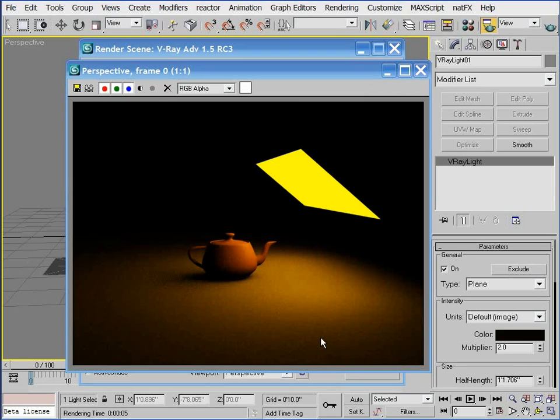color mapping. Values over 4 or 5 is what I consider high. I don't mean to say you can't use such values. I'm just saying that you should be careful when you use such high values because you're almost certainly going to have to use higher quality settings to achieve the same low level of noise that you would have with higher intensity values for your lights.